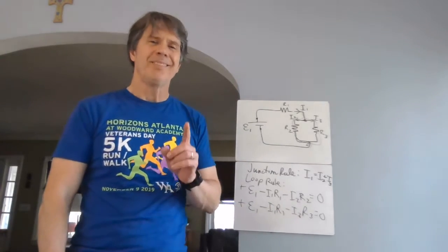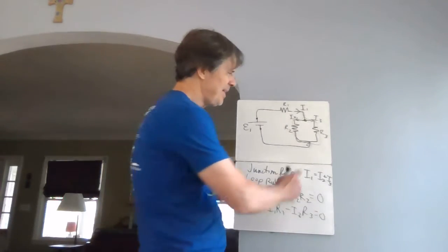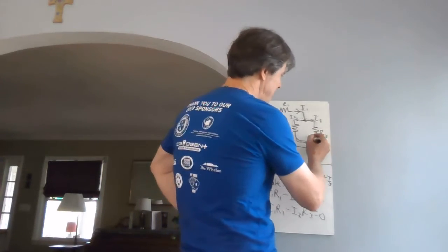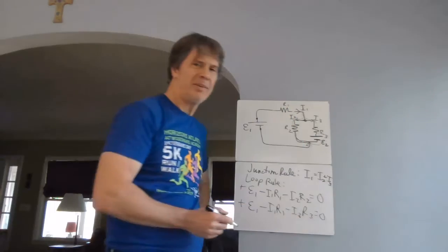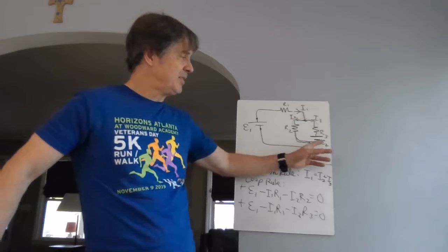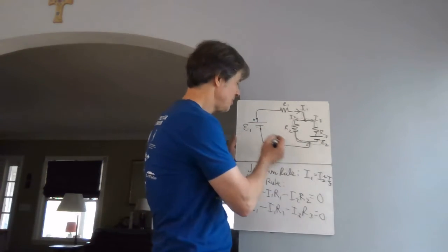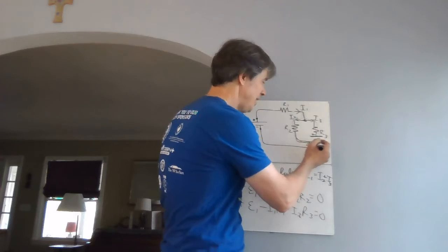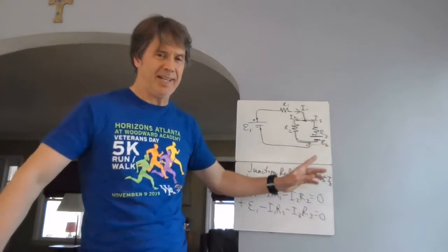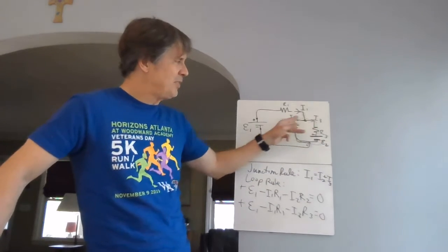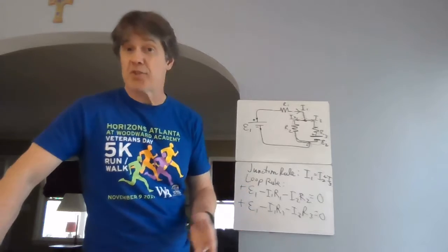Pointless. Nah, but wait. I could really mess things up by putting another battery here that I'll call E2. Now, I might put it in this direction. By the way, whenever you draw, the longer line is the positive, the shorter line is the negative terminal. This is acting like a pump, attempting to drive this current in the other direction. It could, if it's a strong enough pump.